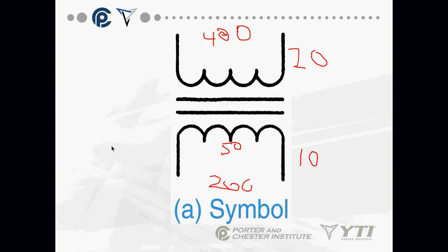So in this scenario, if I'm putting 10 amps in here, okay, if I'm putting 10 amps of current into this side, and I'm increasing the voltage, I'm decreasing the current. So that's something to be really aware of, is whatever my current is on the primary side, depending on what's happening to voltage and the number of windings, it's going to change on the secondary side. Okay, this is very important to remember when we start talking about control systems, because that transformer has to be strong enough to drive whatever controls we're driving.